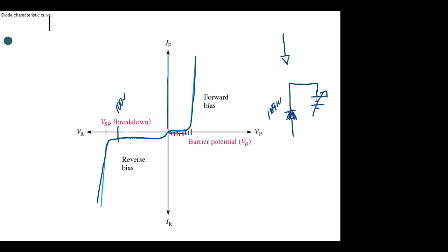So what we'll do, we'll hook them up in series aiding. I don't understand series aiding? Did y'all go over that in DC? Yes? So we'll just hook them up like this. And of course, what happens is their voltages add together, right? So I think we're going to use 4, which might have to be 5. 4 of them would get us up to around 130 volts.